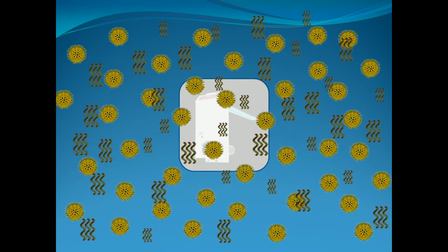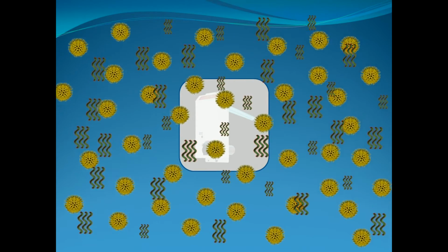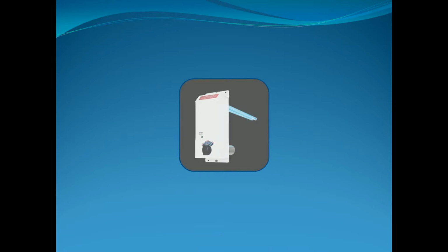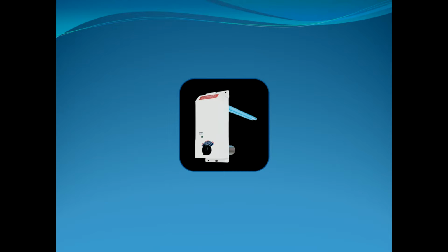Right. So by the time that ozone is actually oxidizing the gases and odors within our HVAC system, by the time it goes through the filter or the air cleaner that might be in there, by the time it goes through the blower motor and the evaporator coil or the heating and cooling coil that's in there, most of that ozone is getting used up. So that by the time that air is getting supplied back into our homes, if you had an ozone meter and you were trying to read the levels of ozone, you're going to read virtually 0 parts of ozone being supplied back into that home environment.